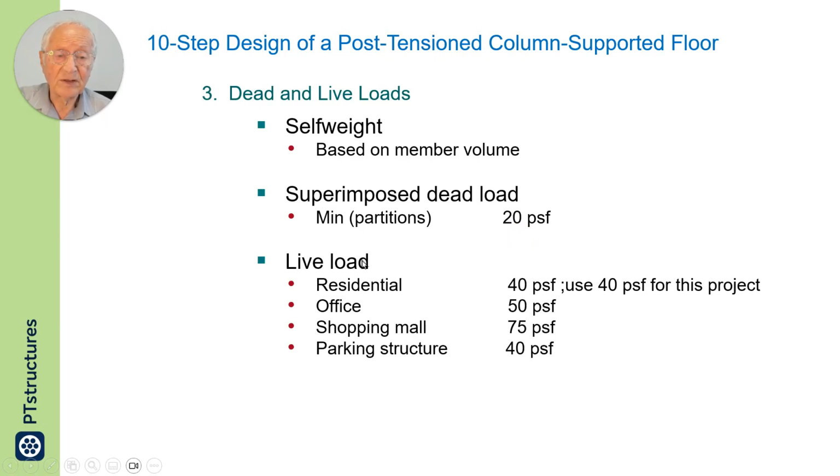And for the live load for residential, I have assumed 40 pounds per square foot. Office is more, and then shopping mall more. These are the common values for a live load assumption. But for this example, I have taken 40 pounds per square foot.